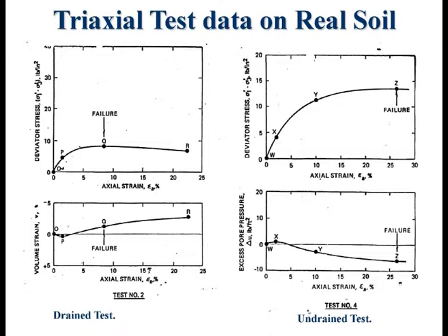And so basically, there are certain instances where you can justifiably use an elastic material, if it is a good rock material, or even very hard soil. But usually, even for very hard soil, we play it a bit safe by using some kind of Mohr-Coulomb. Although there are some issues about how you're going to fix the parameters for that, even for Mohr-Coulomb, if you want to use it. But essentially, we can discuss a bit more on this later on. But, okay, so this brings us to the end of the elasticity part, okay?